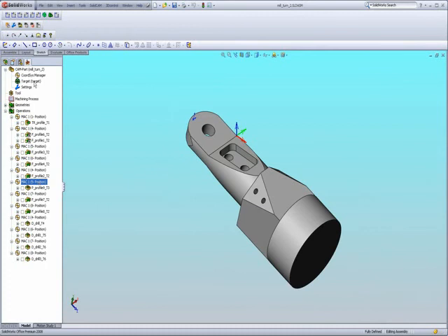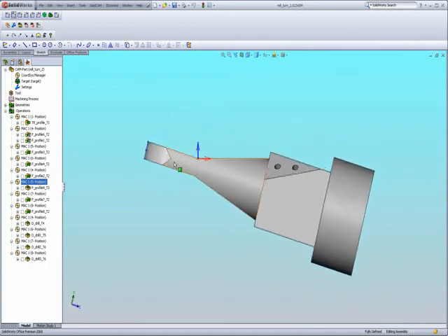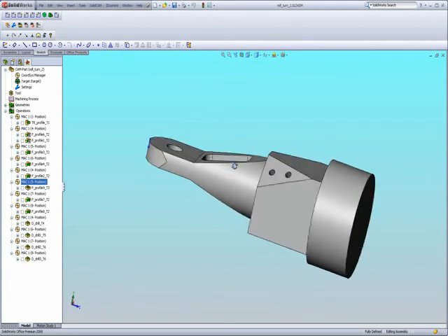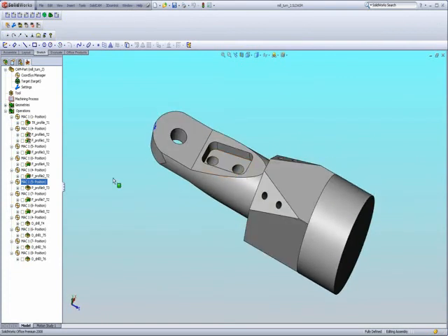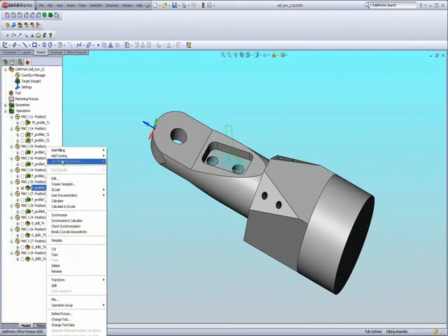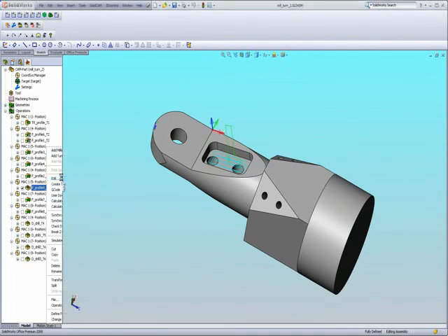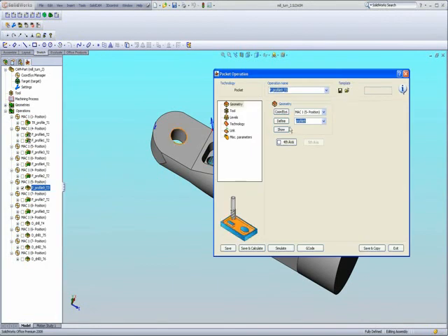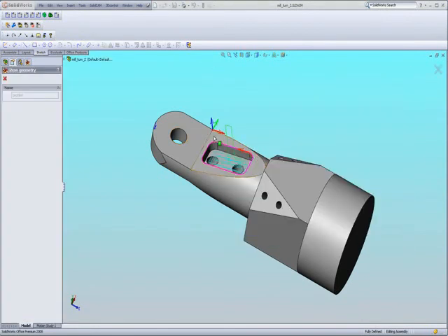For example, this position over here, looking at it from the side, I have to work on this face over here, Mac 1 position 1, and I have to do the pocket that's over there. So simply create a pocket operation using Mac 1 position 5, where my geometry is again this boundary as seen over here.